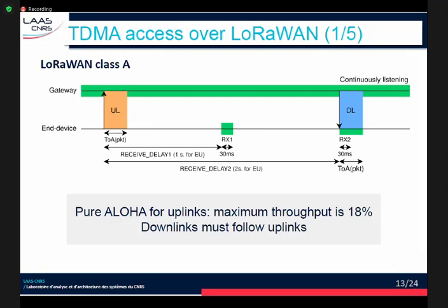If there is nothing there, there is also another reception window where a frame can be received. But of course, this communication is bidirectional, but it's not symmetric. Because if a server or someone from the gateway wants to push some information to the end device, it has to wait to be contacted first, to send something and piggyback it into the acknowledgement.